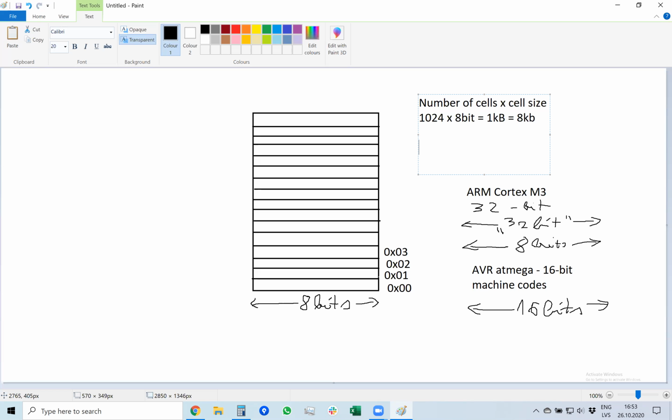So you can actually buy 16-bit memory as well, and maybe even 32-bit memory. I think that probably you can buy 32-bit memory as well. It's just less popular. So for example, you go online and you can buy, for example, 256K times 16-bit. This means each location is not 8 bits, but 16 bits. And you have 256 times 1024 such locations.